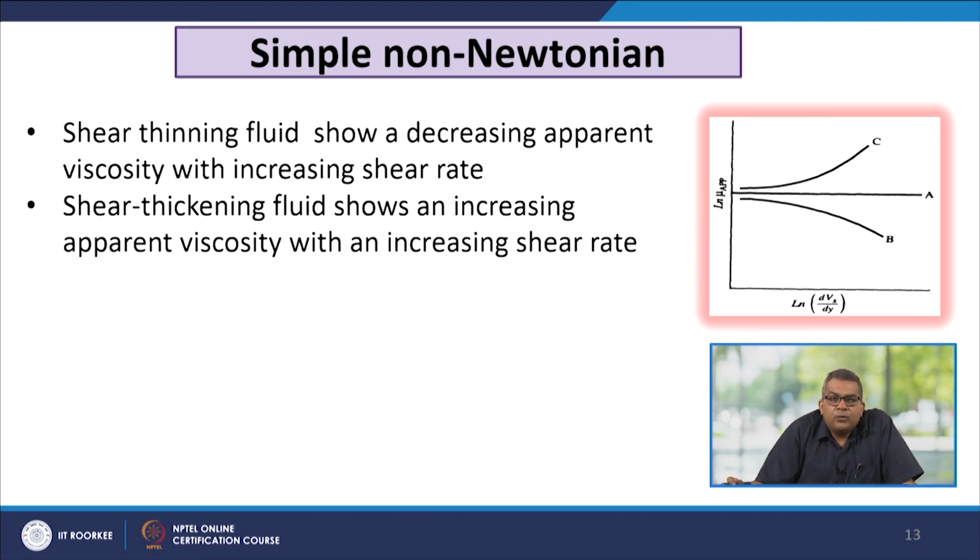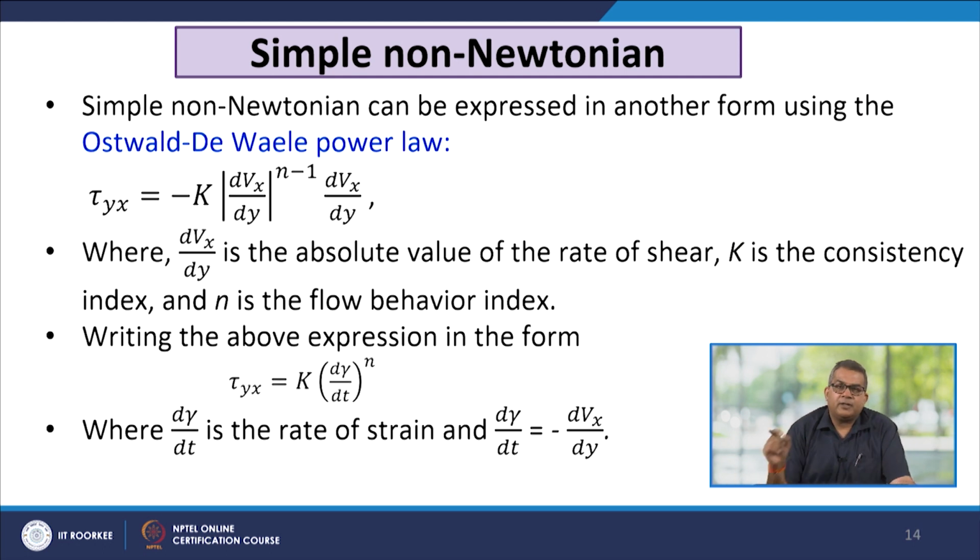Now, shear thinning fluids show a decreasing apparent viscosity with increasing shear rate, and shear thickening fluids show an increasing apparent viscosity with an increasing shear rate.